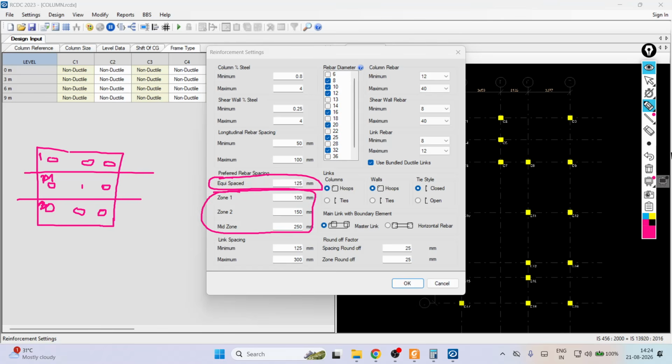So we can see whether it is working or not first. We have to put the value here. It is not accepting. Why? Because here it's saying the maximum value we have to keep is 150, because zone 2 is 150, the minimum is 150, and the permissible range is 150 to 600. Why is the maximum going with this? If I put 100 here, then will 75 be taken? No, it will not take. We have to keep this 150 at least.